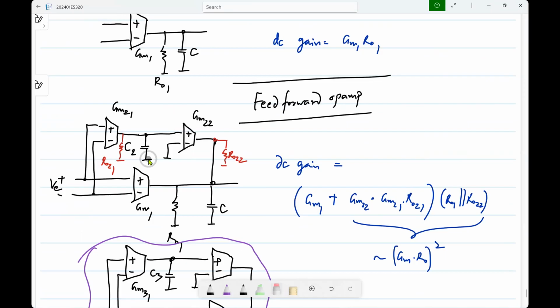So this means that this additional parallel path has to be slower, because if you do this while settling, it could be reacting to something other than the steady state error. When steady state has not been reached, VE is not 0, right? Then you could have two loops fighting each other. Ideally, this should reach steady state, and then you let the second path come into the picture and slowly reduce that error to 0. This gives you the intuitive idea that this path must be slower than that one. Okay. Is this fine?